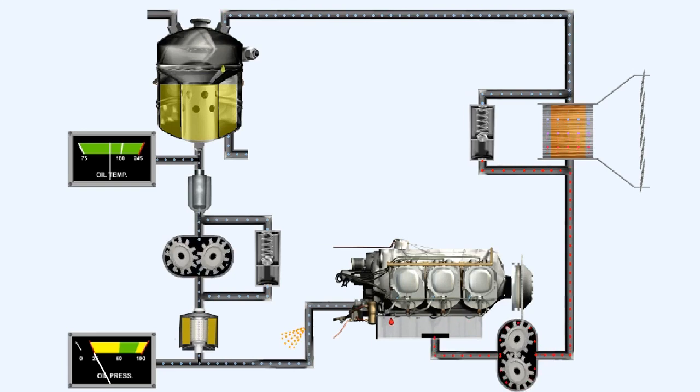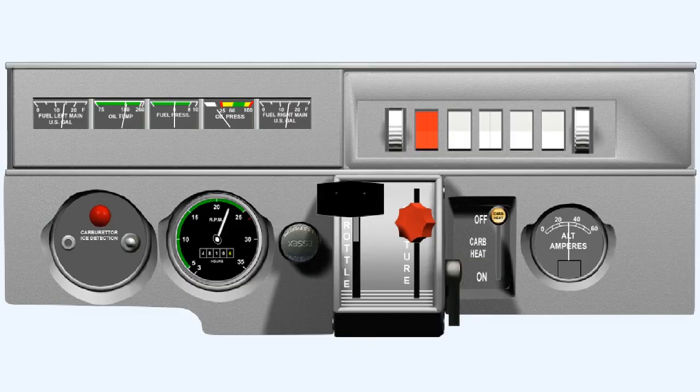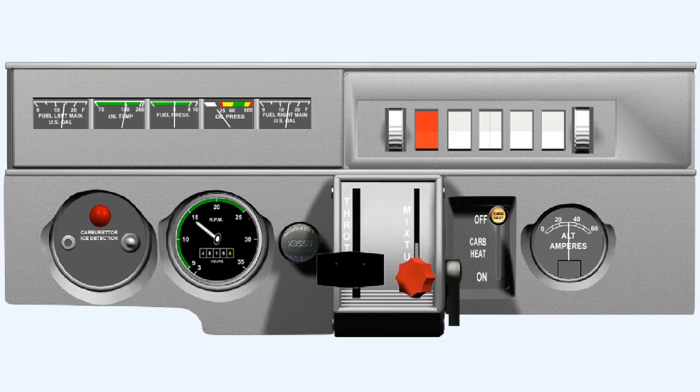If the oil temperature is within its correct operating range and the oil pressure is still indicating that it's too low, then it's likely that there is either excessive clearance on the bearings due to wear, a defective pressure relief valve, or, potentially even worse, leaks from the output side of the pressure pump. If the minimum oil pressure cannot be maintained, then the engine must be stopped to prevent damage being caused to some components through lack of lubrication.